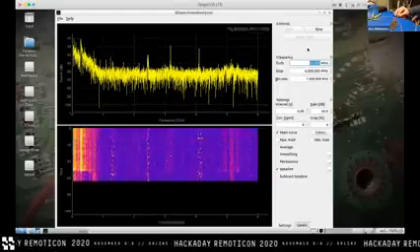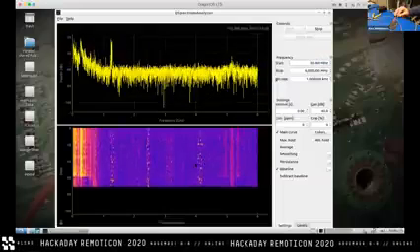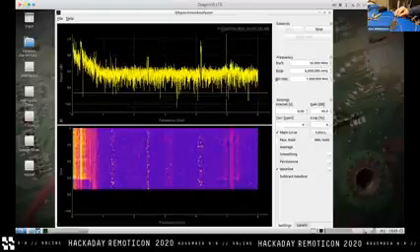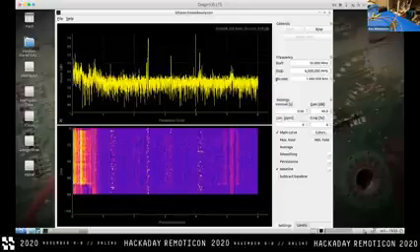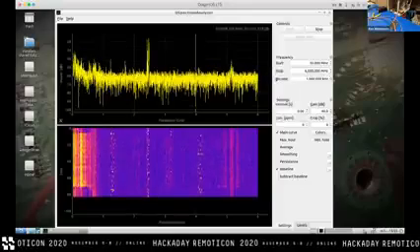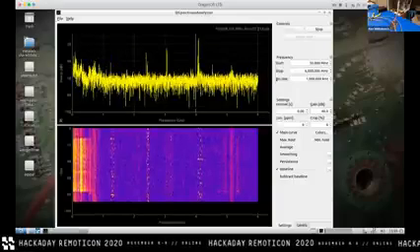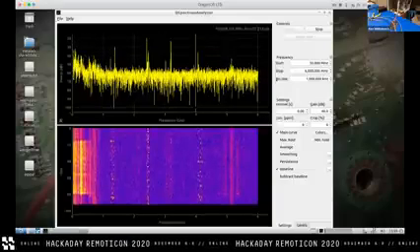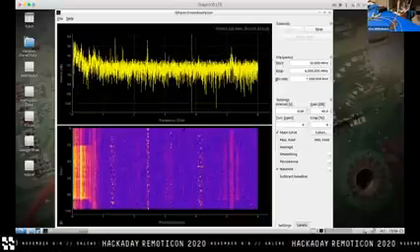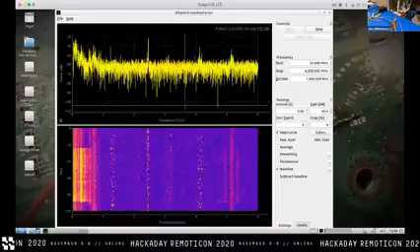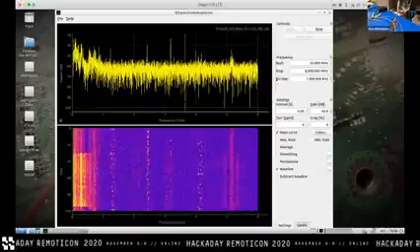I honestly don't know what that 4 and change gigahertz line we're seeing in this region is, and so on and so forth. But you can imagine that if you were in an all clean RF environment and you were just knocking around your board with a near-field probe trying to find this stuff, you will probably have a relatively easy time of it with the HackRF and HackRF sweep enabled. And you can do this with the RTL-SDR. It's just a lot slower and less convenient. So all sorts of options.